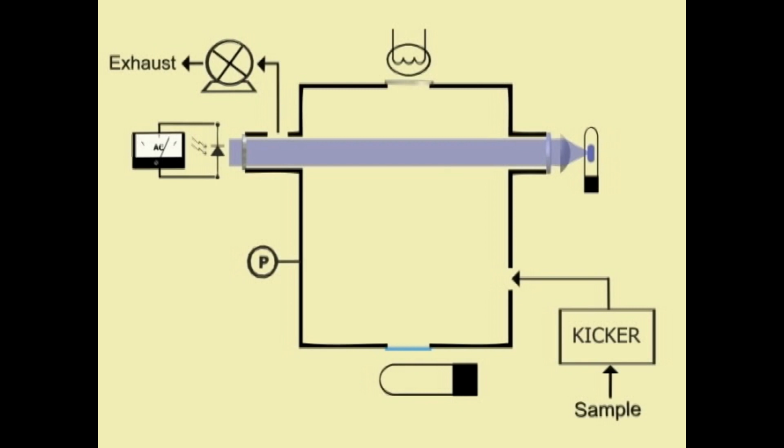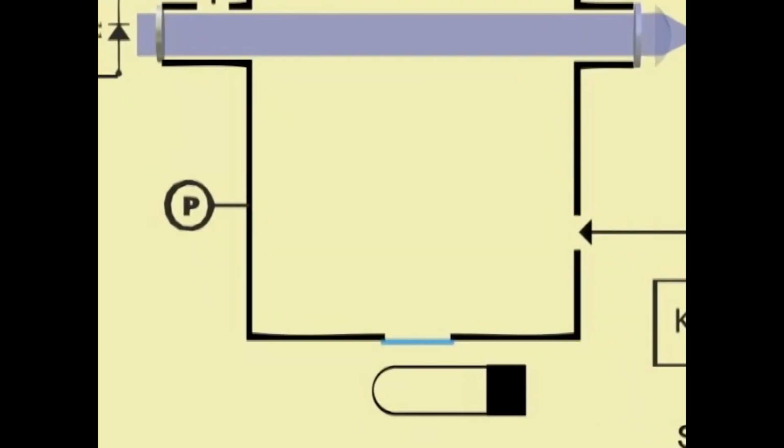One possible solution is to place a high-concentration NOx cell in the UV light path. This approach serves to absorb any UV wavelength that might cause NOx to fluoresce prior to entry into the measurement chamber. However, the preferred approach is to retune the process to measure light in the 360 nanometer wavelength. SO2 doesn't fluoresce as much at this wavelength, but NOx response is significantly less. The end result is that we sacrifice some SO2 signal strength for NOx rejection.